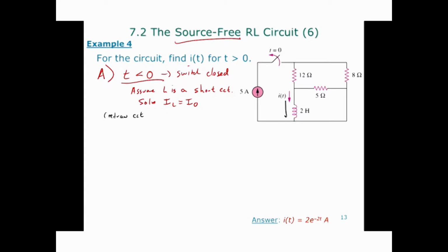So I0 is the initial current going through the inductor at t equals 0. In other words, if we called this IL of 0, that's considered I0. Whatever current was flowing through the inductor at time 0, remember the inductor wants to keep things the same. So when that switch opens, it's still going to try to keep that current flowing at the same rate. Whatever it was doing before the switch opened is what it tries to maintain. Of course, it starts losing energy because that energy is now dissipated through the resistor, so little by little the voltage drops based on the time constant of the circuit.